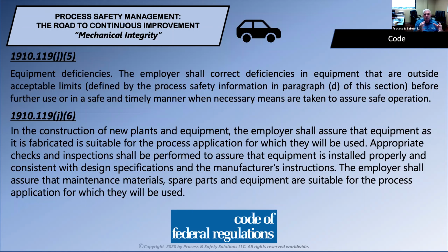The last thing, and this is the thing that also often gets overlooked as well, is talks about the construction of new plants and make sure that the appropriate checks and inspections have been performed. This is where that PSSR that you conduct should fall into place, and making sure that that is done correctly to make sure that your mechanical integrity inspections are done correctly as well. This is where we also pick up your spare parts and making sure you have those spare parts in your stores or readily available, and making sure that those spare parts actually fit those design criteria that you laid out